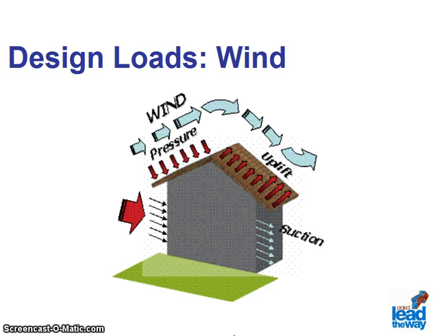Wind loading is another design load that has an impact on the design of the structure. Wind loads can vary depending on the location and the height of the structure. This is referred to as the exposure categories in the building codes. For low-rise buildings, the wind load can be transferred through shear walls such as masonry wall in an elevator shaft and the exterior masonry wall or steel bracing in the structural frame. For a tall structure, the wind can force the building to lean sideways.